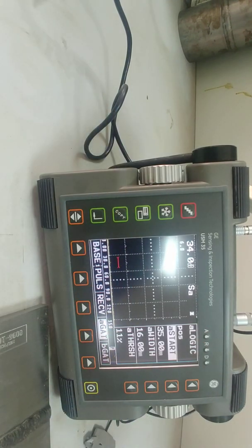Now the next step is, what range value should I set? So you can see we calculated full skip distance as 32. So range should be more than this full skip distance, because we want to see actually two legs. So what I'm going to do, I'm going to add something like 12.5 mm, half of the inch, to 32.5, just some extra length. So this is 45. So my range should be at least 45 millimeters, so that it covers the complete area.